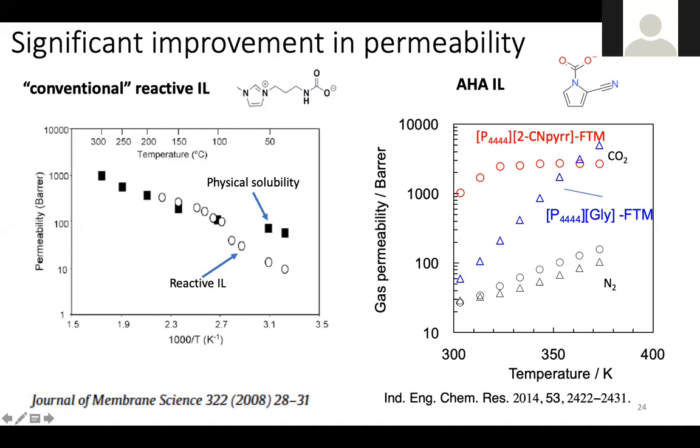Then the other, I know one thing about that. We have a large ethanol plant here in town. I've given tours. They use adsorption. They use zeolites to break the azeotrope. So they do an adsorption-based separation. And so that's an example, I think, of where it is pretty clear that if you can do adsorption or membranes, you could think about a pervaporation membrane, you're going to definitely save energy versus distillation. There's a whole other question about if bioethanol is really helping you all that much, and that's a whole other topic that I don't really want to go into right now, but that's a really good point.